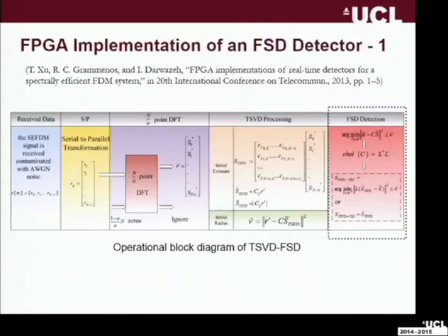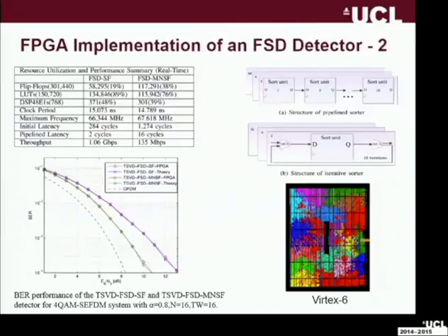And talking about implementation, because, okay, we did a transmitter, we did a receiver, but we hadn't actually implemented the sphere decoding on the FPGA. We really wanted to see what kind of circuit complexity that would take up. So we decided, okay, that's the next stage. And this is the part here in the dotted boxes that we actually implemented on the FPGA in isolation.